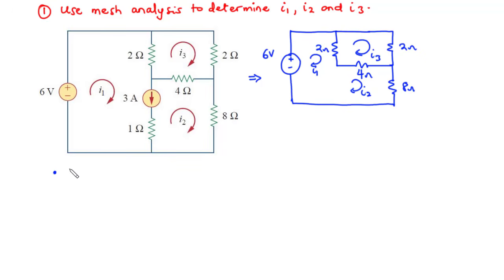So we have the source voltage, which is 6, equal to the sum of the voltages dropped across the loop. Now, moving through this direction, in this branch, we have I1 moving in the clockwise direction, and then I3 moving in the anti-clockwise direction. So the two currents are opposing each other. So we are going to have 2 into brackets I1